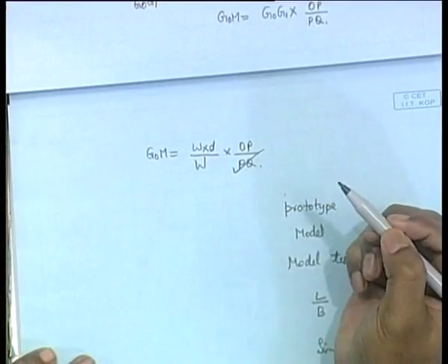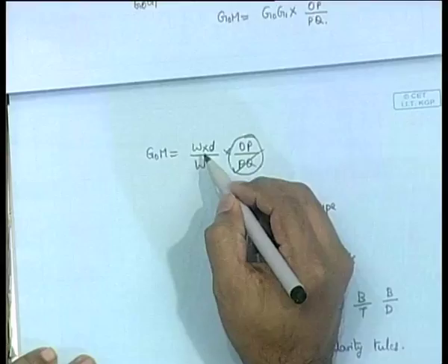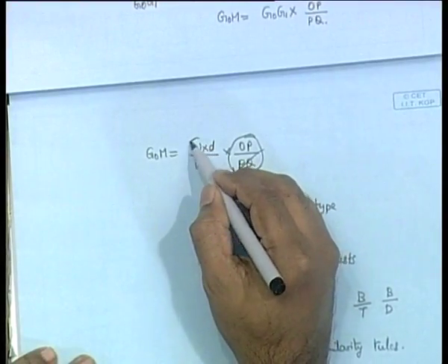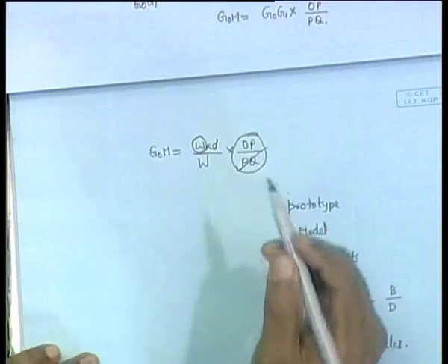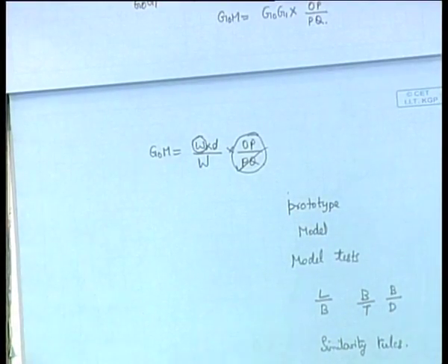Therefore you have two things, this length also you have, this length also you have. Therefore you have the angle that the pendulum makes with the vertical when it is inclined, or according to this derivation you will have OP by PQ. Okay. So once you have this, another thing you need is the weight that is moved, this small w. So what you do is you take a known weight. Actually the way in which it is done is, there are weights, you have seen in a measuring balance, you put weights on the right side and the material on the left side, like that. So those weights are there, like 50 gram, 100 gram, 150 gram.